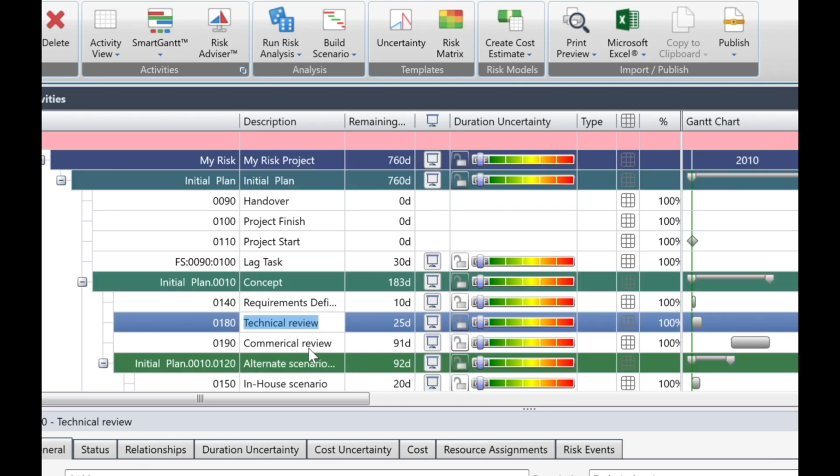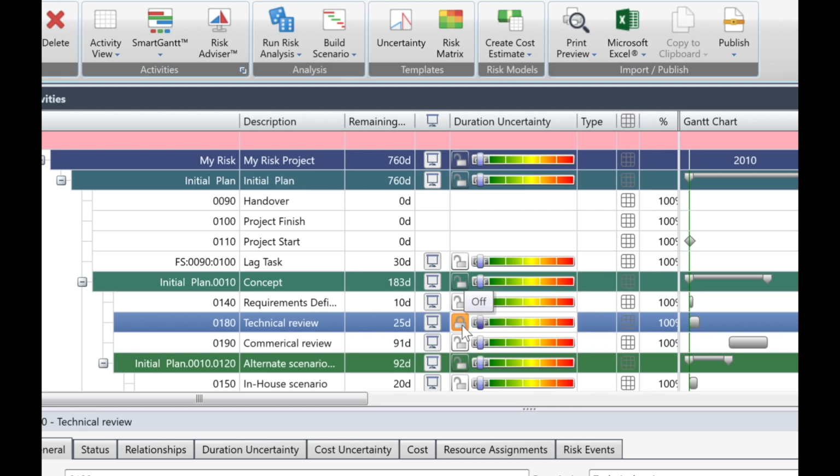Then click on the pull-down for its distribution type and select Normal. You will note that the slider becomes locked and grayed out. To activate the slider again, drag it to the left or right and return it to its original position. You'll see that the distribution type was automatically reset. But you'll need to click the lock icon to unlock it again.